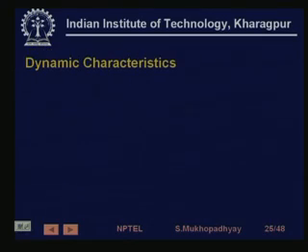Now we come to, so this more or less completes our static characteristics. So generally we talk about an input output curve, right? That is a calibration curve. So there is no time here. If we give an input, we will get an output in the steady state, and we are only talking about the characteristic between this input and the steady state output value, right?